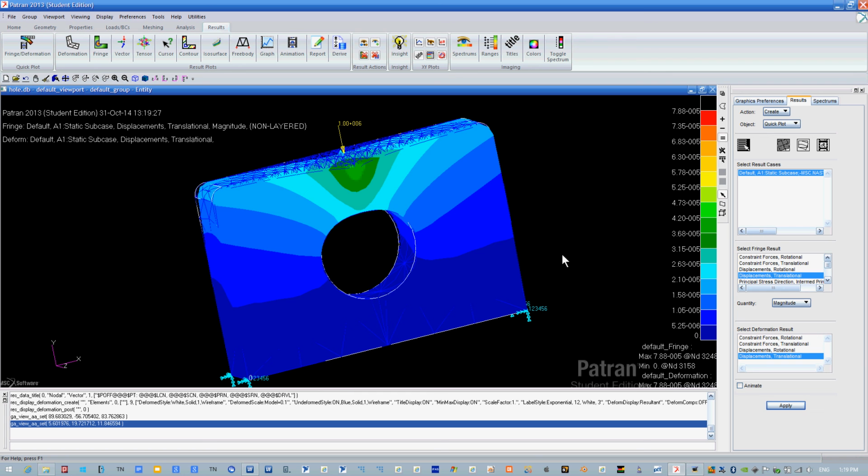But yeah, what I was saying earlier is, if you have a right angle in your structure, you want to make sure that right angle is rounded. Any sharp point within your structure is going to be a point where, the more nodes or elements you have around it, you essentially balloon that value off to infinity. This only applies on the inside. On the outside, if I didn't have these fillets up here, that's fine, that's not an issue. But if this inside here was a cube instead of a cylinder cut out, then those four corners inside the structure would need to be curved.